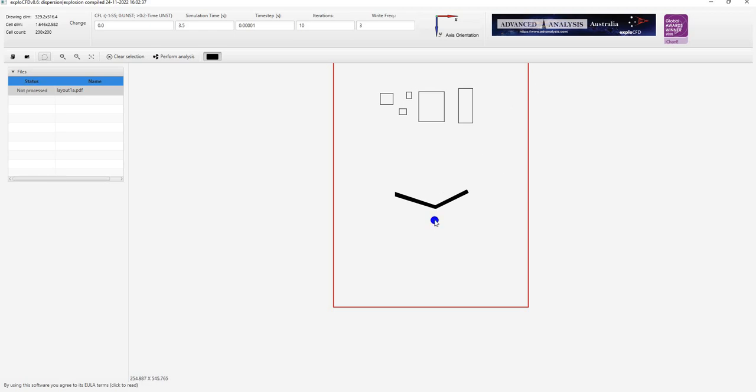So I'm going to place the footprint of the gas cloud. Now, ideally, this gas cloud should be of the appropriate dimensions. It's usually, in industry, in all CFD, taken to be a rectangle, just for ease, but you could modify the shape of the rectangle by holding down the Alt button and reducing the gas cloud dimensions from various sizes.